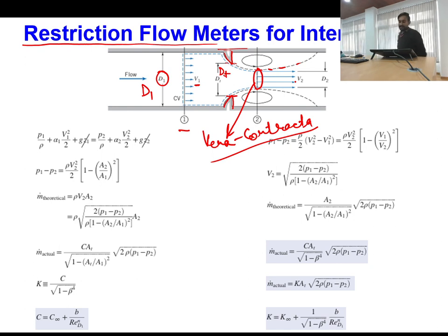Okay, and above and below this region, you will find some recirculatory fluid pockets, where some fluid medium is continuously recirculating there itself only, and the whole bulk fluid which is entering is only passing through between the dashed lines.